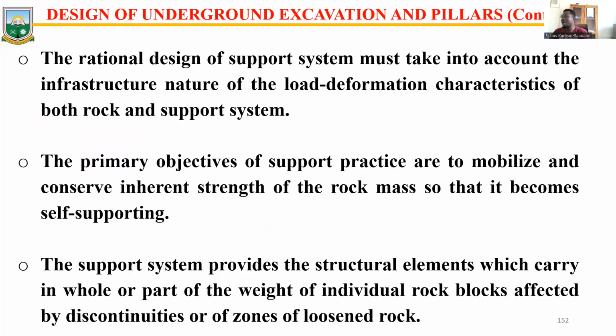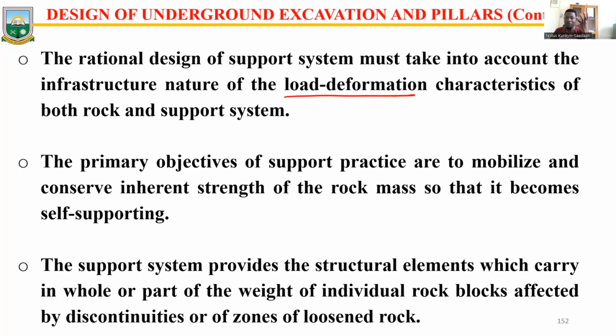So for example, I want to design a support for an underground stope. What do I need to consider? The main idea here is that I have to first look out for the load deformation properties. That particular material that I want to support, how does it behave? Does it have some kind of tensile strength? What kind of failure is even occurring within the material? So I need to understand these properties of the formation.